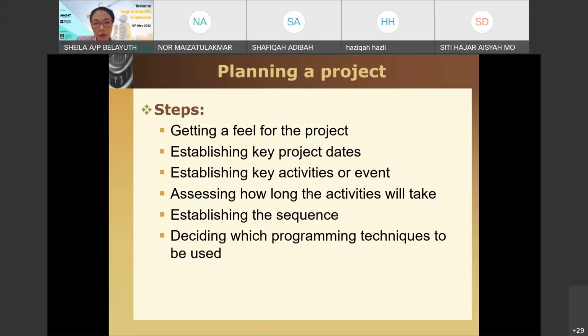That depends on the resources you have in hand, and how long it will take to complete with those resources. For example, if we are talking about earthwork activities, and you only have 2 excavators, obviously your duration will be longer as compared to someone who has 5 excavators. So the duration depends on the resources and machineries you have in hand, and also on how long it normally takes. Usually this comes with experience. Someone with experience will say that on a daily basis, a truck would be required to carry so many meter cube, more or less. So sequence and duration usually rely quite a lot on experience.